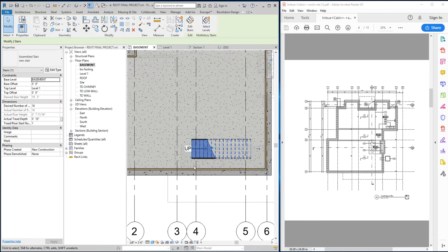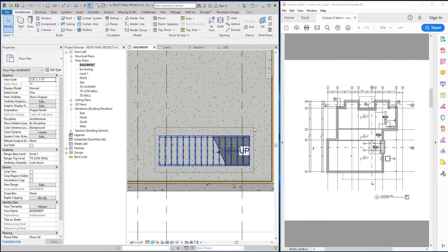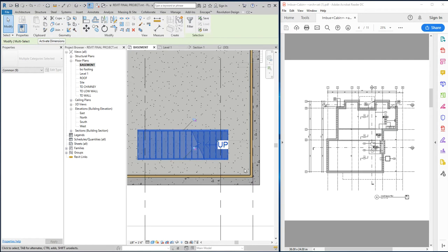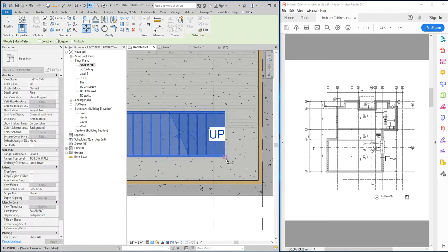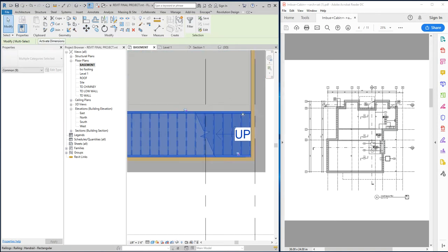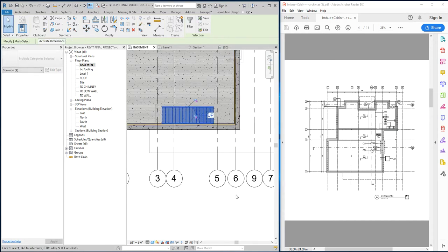So I changed the orientation of my stair. Now this is the bottom, and it goes up that direction. What I'm going to do to move it, just move like moving anything. Get some pins. MV, move. Click. I move it down into the corner, and then I'm going to move it where I want it to go. So I'm going to MV. I think you only need it 3 feet, but I'm going to move it 5 feet away from that wall.